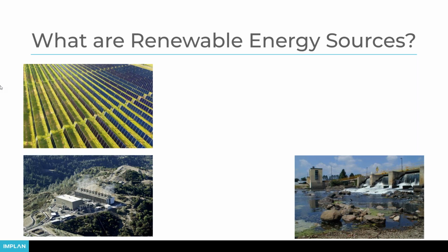There are 3 basic types of geothermal power plants. There's a dry steam plant, which just uses the steam directly from the ground. Flash steam plants take that high pressure water from deep inside and convert it to steam to drive turbines. And then there's binary cycle, which transfers the heat from that resource in the ground to another liquid. That heat causes the second liquid to turn to steam, which then drives the turbine. The one shown here is from the Geysers geothermal plant in California, and that uses steam.